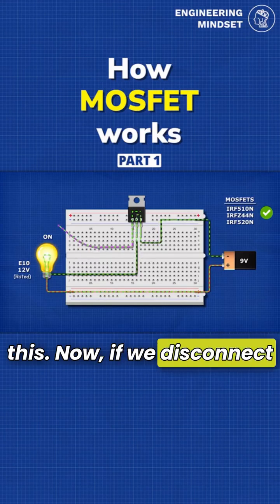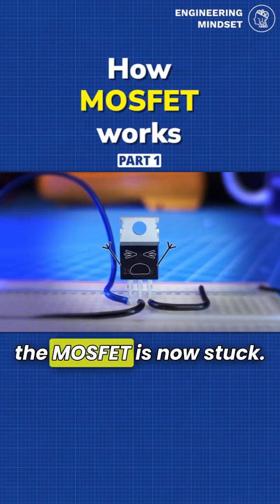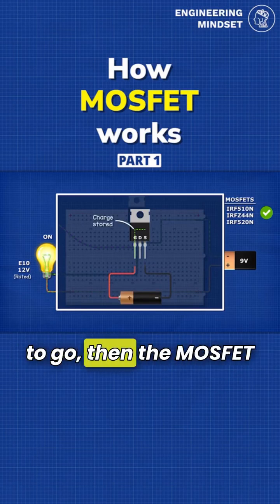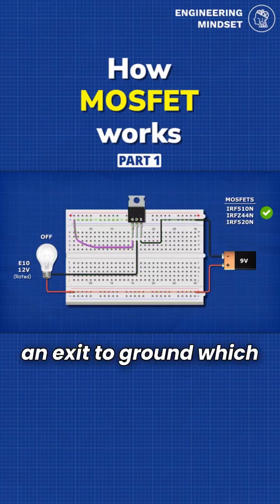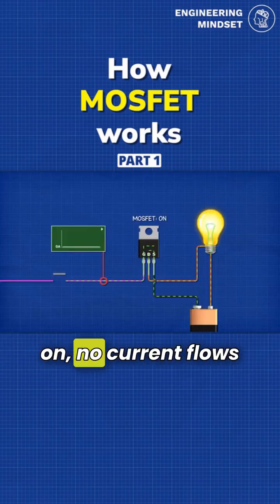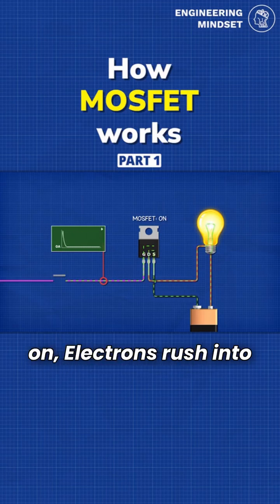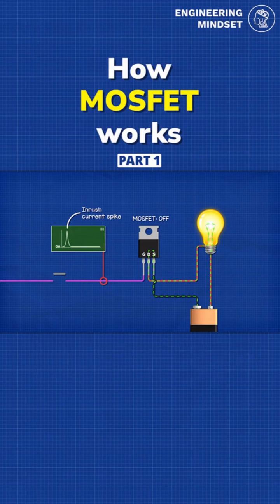Now, if we disconnect the voltage to the gate pin, the lamp remains on, and that's because the MOSFET is now stuck. The gate terminal acts like a capacitor and it stores charge. If this charge has nowhere to go, then the MOSFET will remain activated. We can discharge the terminal by providing an exit to ground, which will deactivate the MOSFET. When the MOSFET is fully on, no current flows on the gate terminal. But when the MOSFET is changing from off to on, electrons rush into this terminal for a split second. And so there is a large inrush current flowing here.